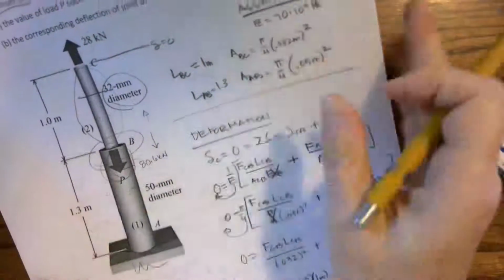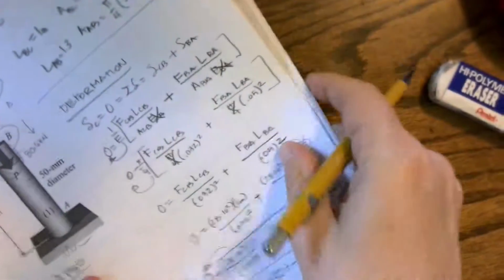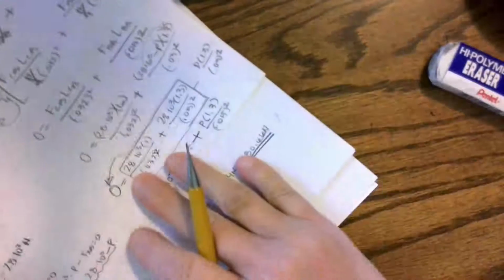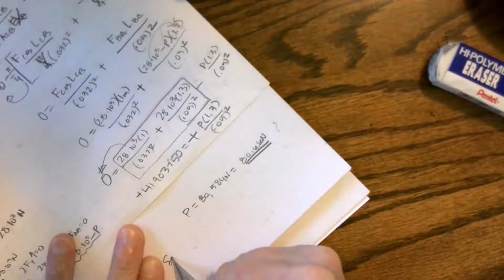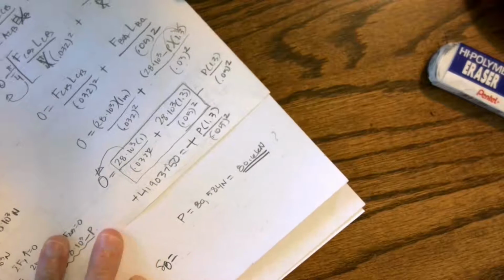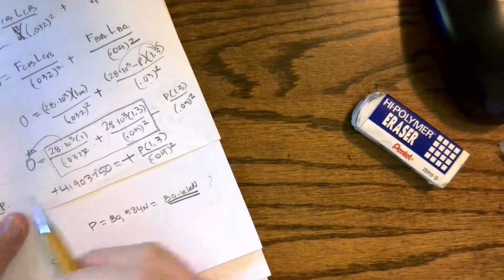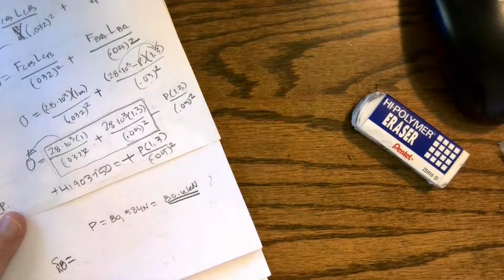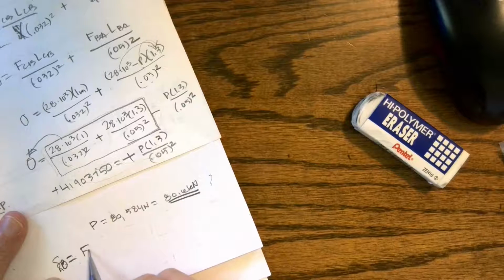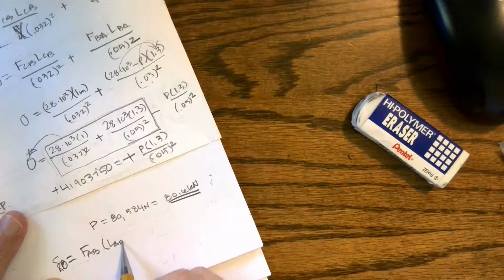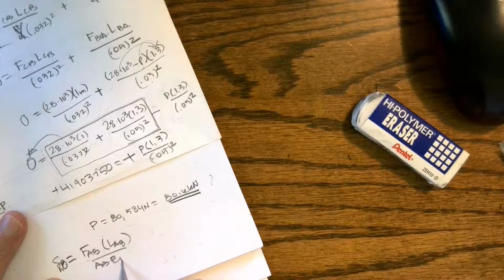So now, if I want to find the deflection at B, so what's happening here at B, okay, then I can look at, sorry, need a much bigger desk and a different camera. Okay, so if I want to find then the delta at B, well, I can look at from A to B, it's fixed. And so if I look at what's happening with A to B, okay, A to B is going to give me what's happening at B. So A to B is going to be force AB, length AB, area AB, modulus AB.